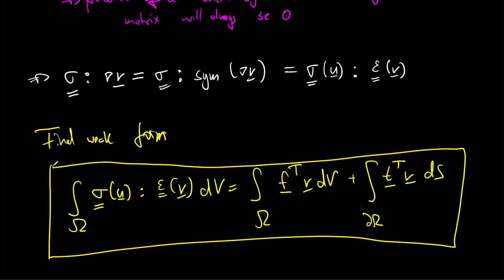That works for linear elasticity, and you can also use it on different cases than just the cantilever beam, because you could also prescribe Neumann boundary conditions, and this allows us to solve simple structural mechanics problems in FEniCS.